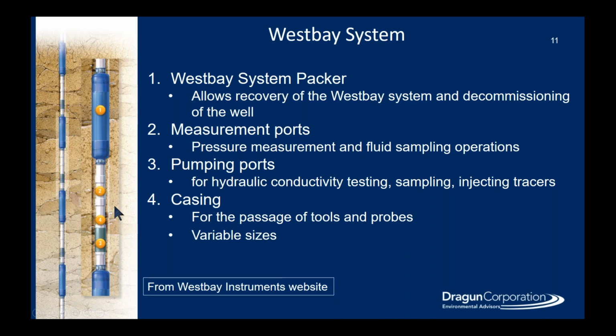And the advantage of this is, as I mentioned, you're able to get a better vertical distribution, but you can also reuse it, because by deflating the bladders, you can pull the system back out of the borehole and potentially use it in the same location again or another location.